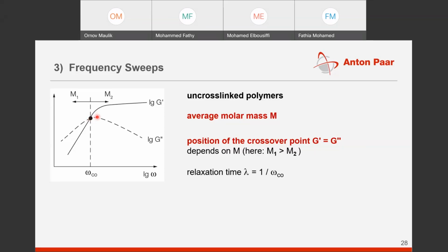So this type of relaxation point is basically related to complete relaxation of the molecular chains that are entangled. So we need to give this much time in order to extrude any particular polymer product.